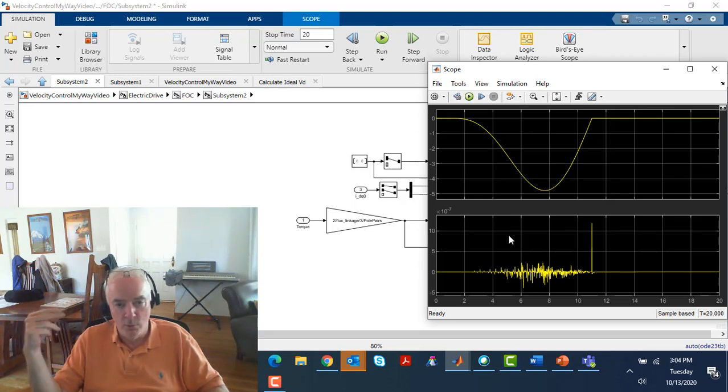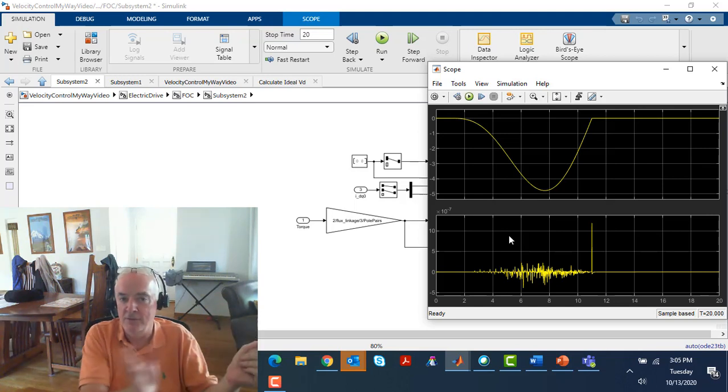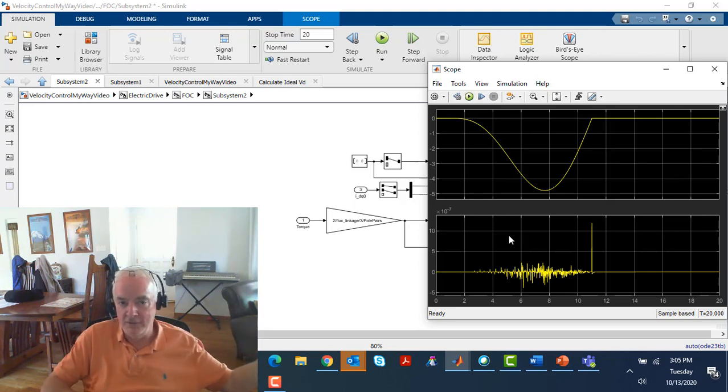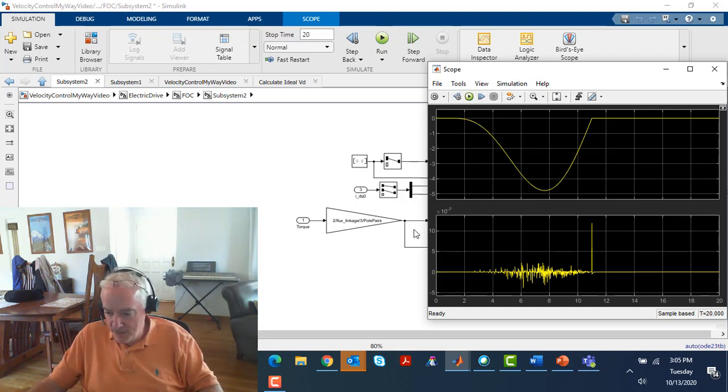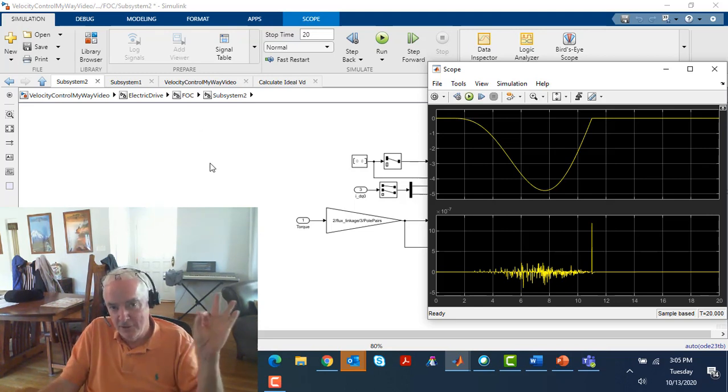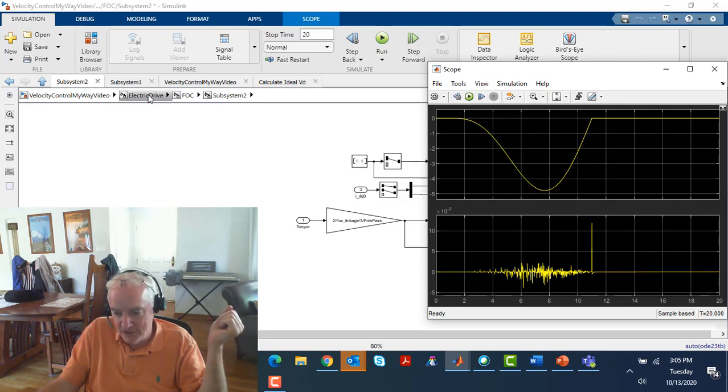Okay, and so in the real world, the wind blows. In the real world, equipment does deteriorate. It's not exactly the same as it was the day before, and certainly not the same as it was 6 months ago. And so PIDs come into play, and they really manage that and make sure the overall system does what it's supposed to do. Okay, so anyways, hope that's clear. The feed forward controls are great, but for them to be successful, almost always you have feedback involved still.